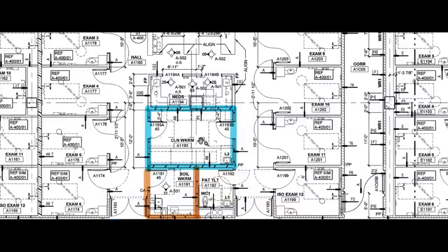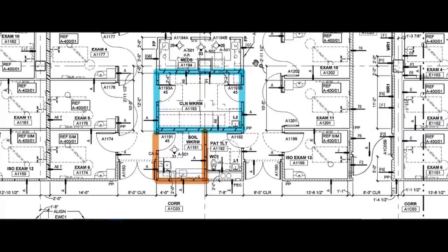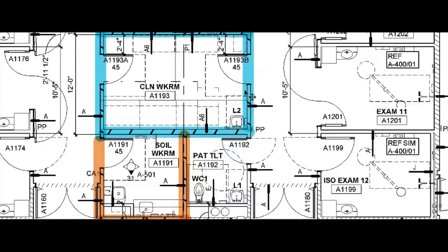Those are the kinds of things that I look for when I'm looking at the floor plans, looking at the overall area, the use, where it is within the building. Certainly pick up the note that it's fire rated. You can see the 1 hour partition here. This architect underneath the door number does list the fire rating. Many architects don't.